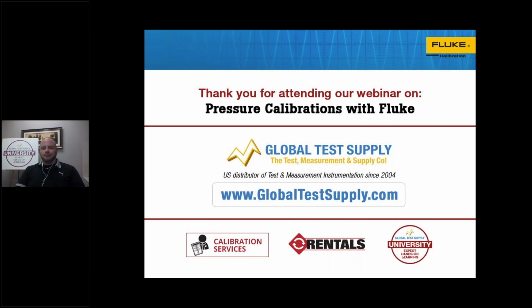And I really recommend you take a few moments to confirm those accuracies, especially if it's a critical measurement. Try not to misapply equipment. Typically, a 300 PSI piece of equipment is generally not intended to work below, say, 3 times its range. So below 100 PSI gets a little bit questionable. Same thing with a 3000 PSI, might be a little bit questionable at 1000. It just has to do with specifications.